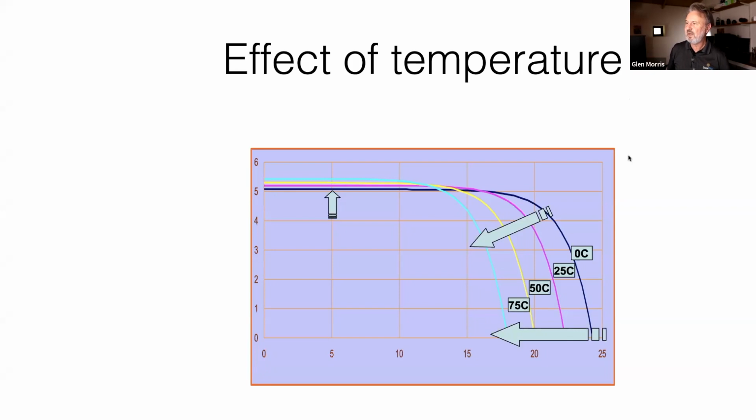And Orb, do you have a link for a temperature effect calculator if one exists? Well, it's actually linear, so your calculator is the way to calculate it, once you know what the temperature coefficient is for a panel. Now, I'm not brushing you off, Orb. I'm actually going to cover this in more detail with some diagrams explaining it in subsequent webinars. But you don't need any special tool other than pen and paper, your brain or a pocket calculator.